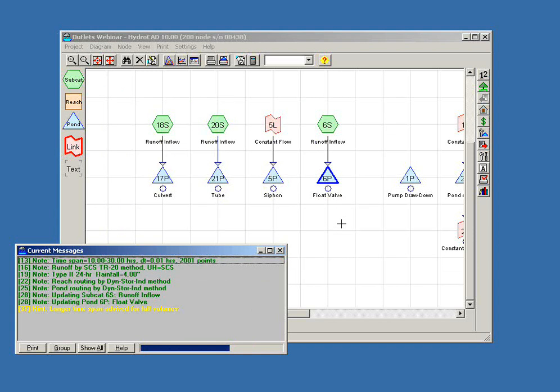Okay, so in this category of conduits, we have culverts and tubes. And again, a culvert is usually considered a partially full conduit, where a tube is based on the assumption that we have full flow within the tube, and we're using it to model other scenarios such as self-priming siphons and even float-operated valves.